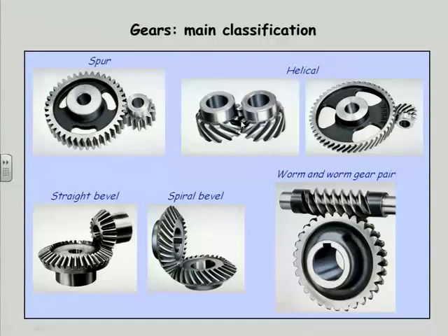Down on my foot. So there I want a worm and wheel with the helix angle small enough that it can't drive backwards. If I make the helix angle bigger, then I may get to a point where the coefficient of friction is not sufficient to hold it, and it may run backwards. It's called a back-drivable worm. But I have to go to some trouble to make the worm back-drivable. Normally they would tend to be non-back-drivable. So for a situation where you need to lock something in place, it's ideal.